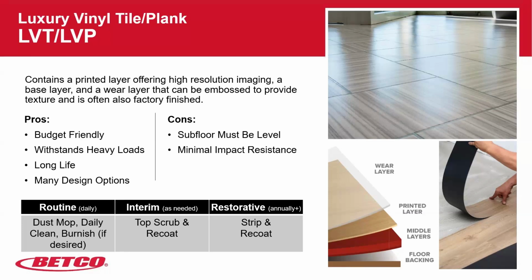If you take a look on the bottom right-hand side of this slide, you'll see what the different layers of LVT and LVP are. And at the very top is a wear layer. And that wear layer is very, very thin. It can come from 5 mil, which, to give you a reference, would be about 1 Post-it note thick. So on most residential floors, it's like 1 Post-it note thick. On commercial, the most expensive LVT is probably about 4 Post-it notes thick, or about 20 mil thick. So it's not very thick.